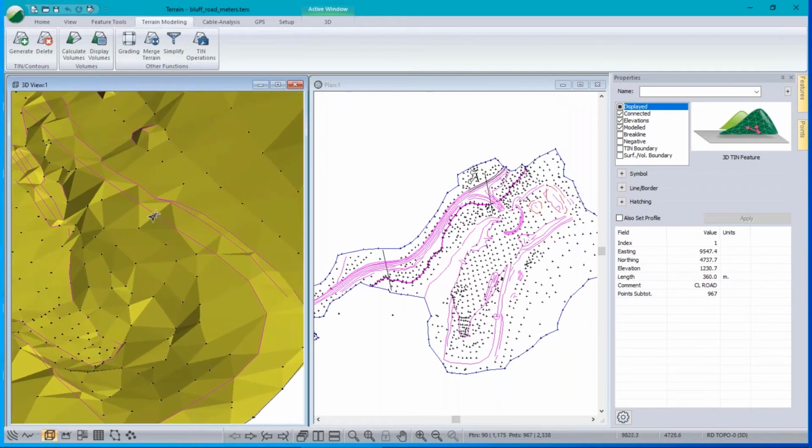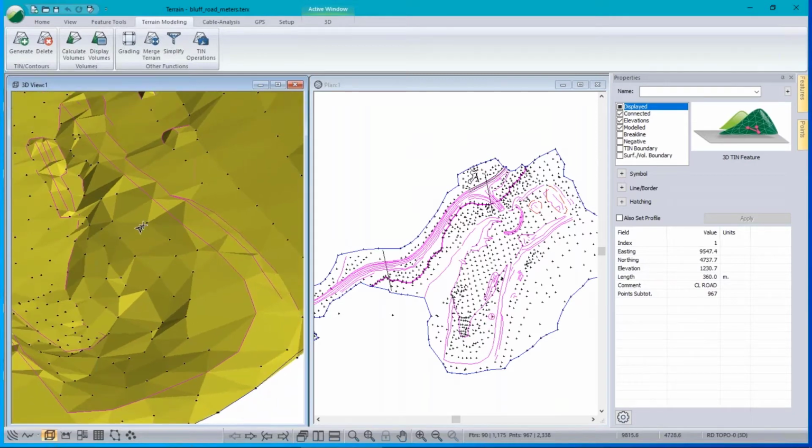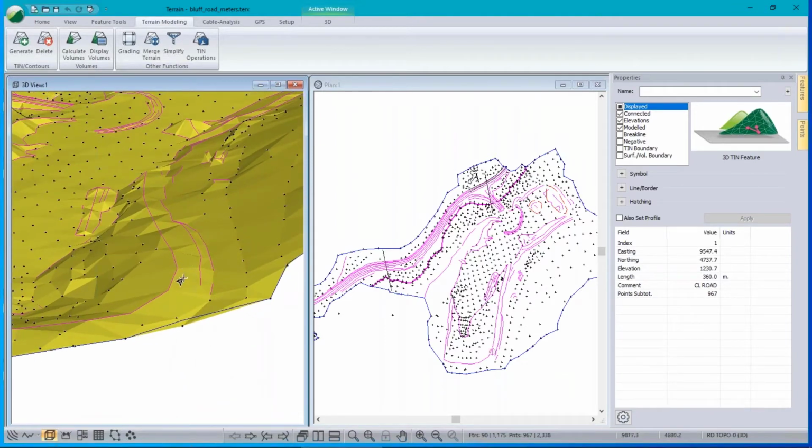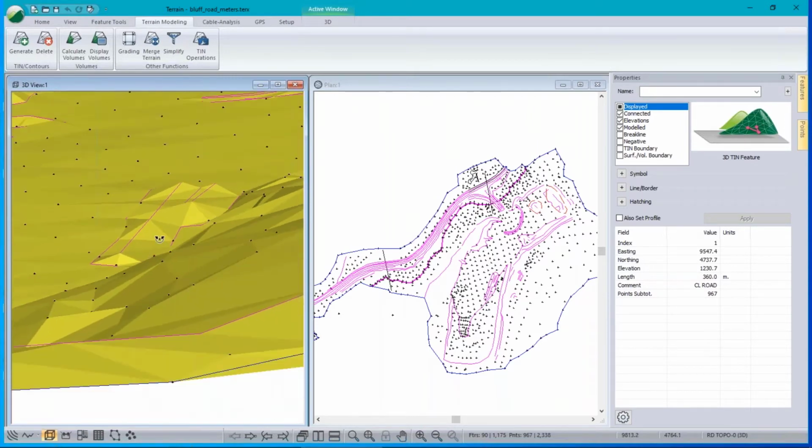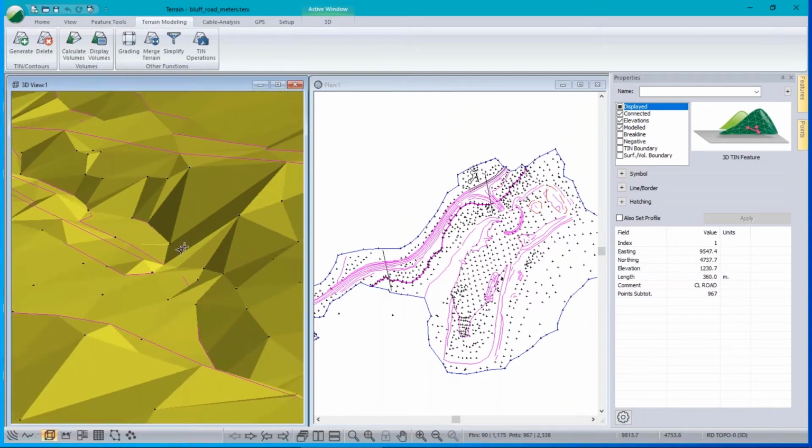There is a classic crossing or missing break line artifact. The surface that's being generated is just going straight through that little piece of road. So it doesn't look like a road exactly anymore. It looks like a road with washouts in it. Similarly, this pile here, that's the pile top. And because the software is interpolating between a point over here and a point over here, the middle of the pile is just gone. It's just not rendered.